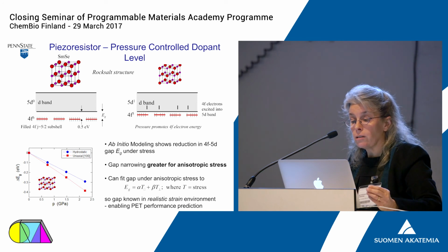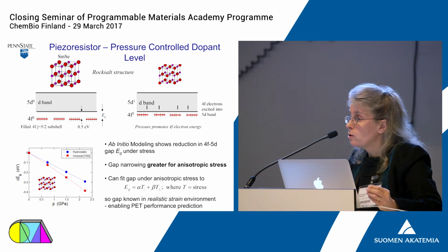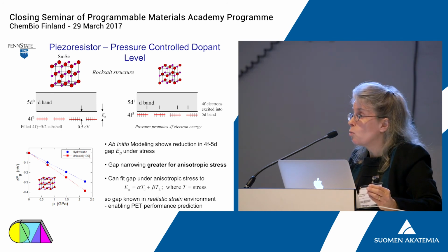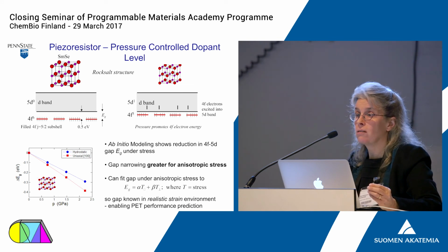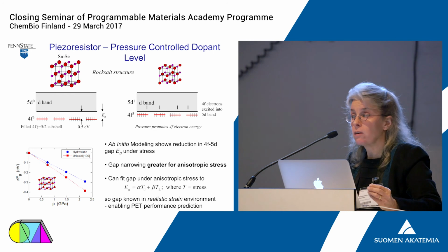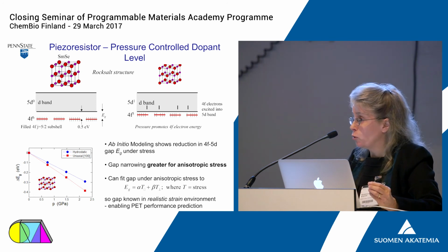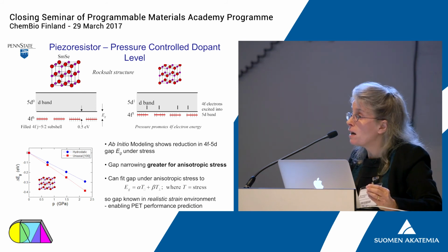Under compression, this f level moves closer to the empty d band so that I can actually thermalize carriers into that band without a phase transition, which means that it is not inherently hysteretic, as would be the case for a material like vanadium oxide with its metal-insulator transition. It still takes depressingly large values of pressure to get a 5-order of magnitude change in the electrical resistance, but it is possible.